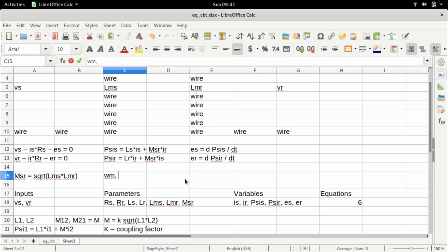The next thing that is quite obvious is the torque. Again, let me put m here, because this is the mechanical torque of the machine. The mechanical torque is the actual load torque, the mechanical work that this machine does, so you can say this is the output torque. Besides this, of course, there is the input torque, because remember, this machine converts electrical energy to mechanical energy, which means there is an electrical torque which is also produced. So we can call this the input torque.